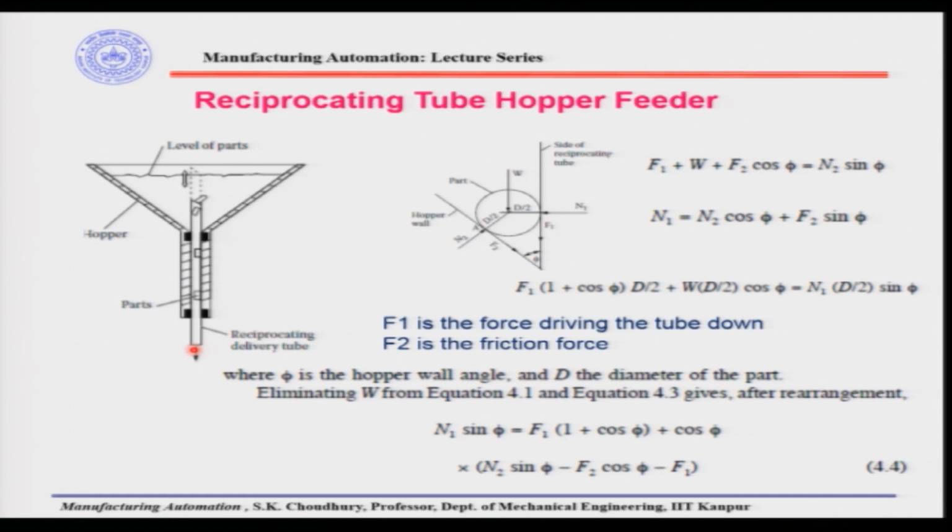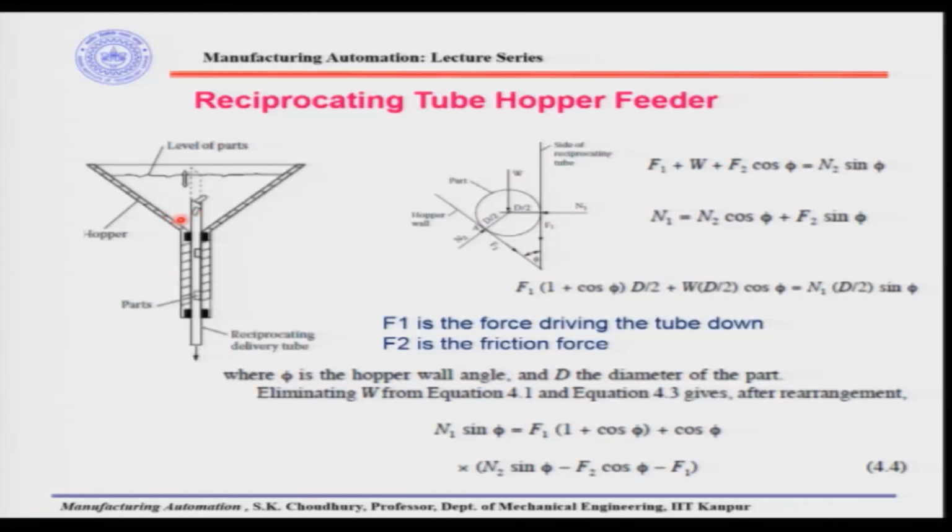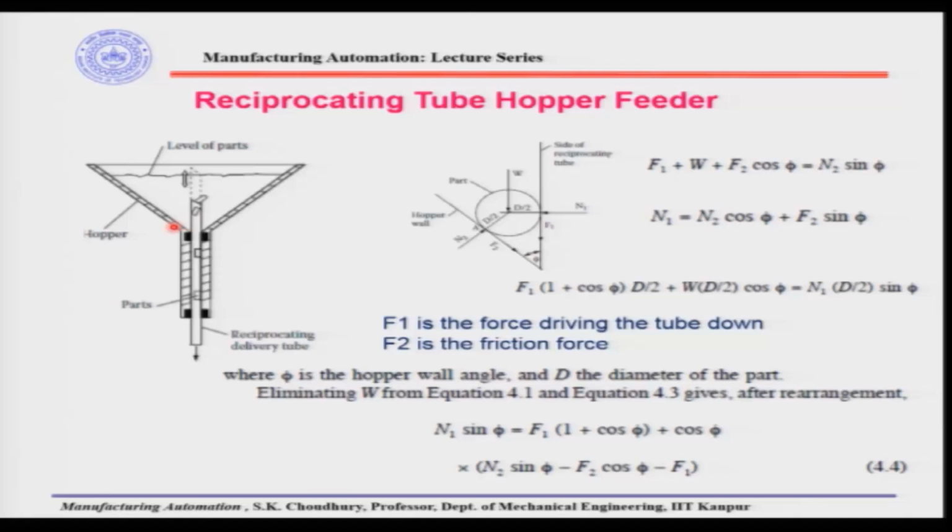Now, while designing this hopper feeder, however, it is very important to see that the parts should not jam between the reciprocating tube here and the hopper wall, okay. That means the hopper wall, this angle should be made in such a way that this jamming does not happen.